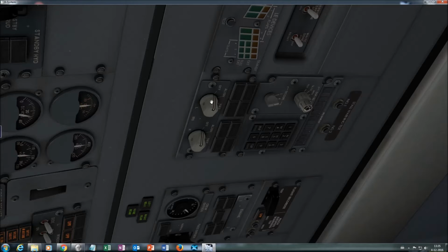And of course, when we start flying, we have to navigate our way from the origin airport to the destination airport. So it's quite important that we have the navigation software online and aligned, and that aligning is what we do now. You switch both of these switches 2 clicks to the right to the nav position. So 1, 2 and 1, 2. It flicks on DC and then to align. It must do that here as well. It does, so that's okay, checked.